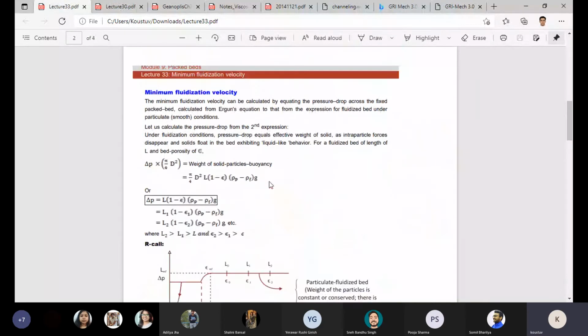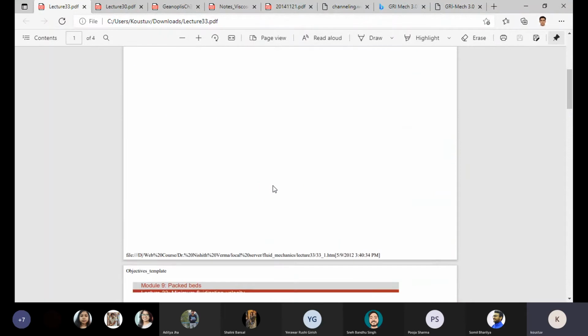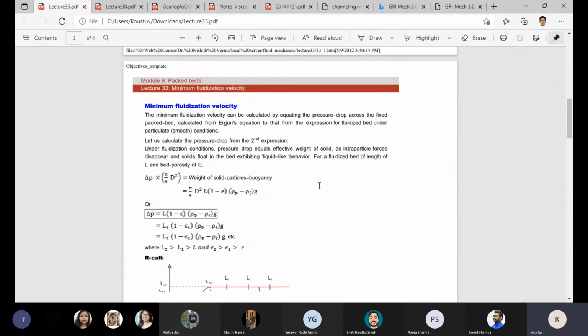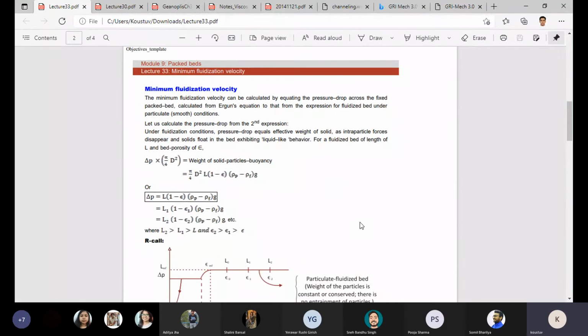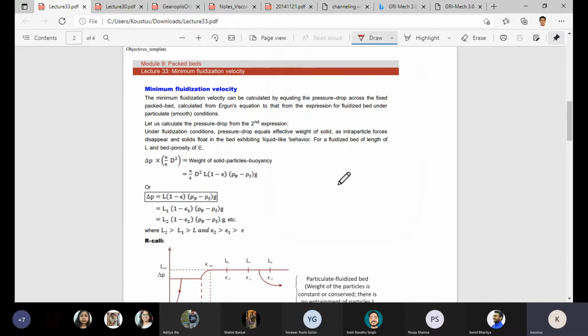And then at the same point, we also have fluidized bed operations. Now fluidized bed operation is nothing but an extension of packed bed operations. So suppose you have the same packed bed, with different packing materials, and you are operating it under fluidized condition.